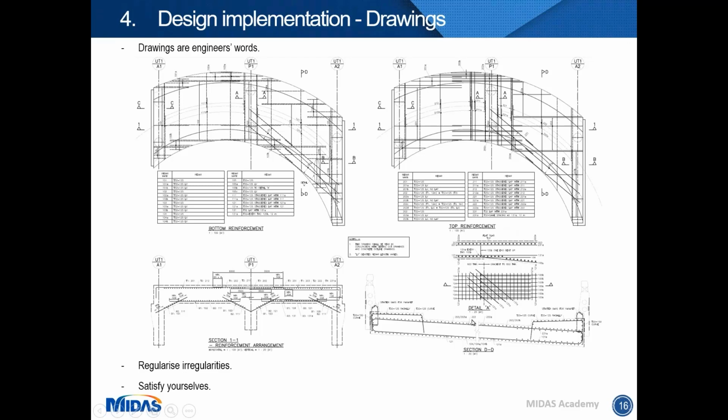My boss actually noticed this before we issued our drawings. So we decided to bend up the ends of the reinforcement from the tapering zones so that they would have proper anchorage. At the end of the day, if the drawings have not captured this, either if the contractor is good enough, they will come back to you asking how to treat the reinforcement at this area, or something else will happen. So that's why I think drawings are important.